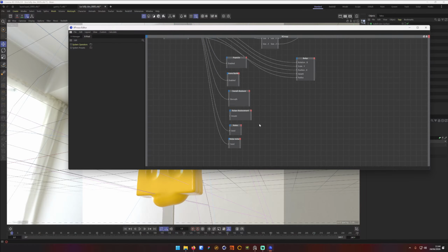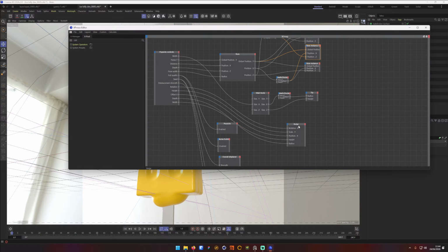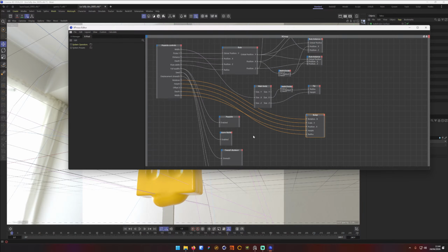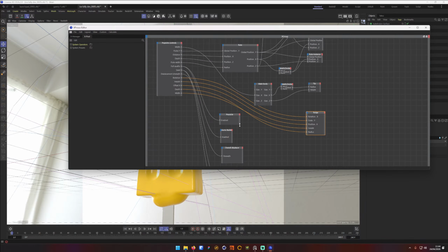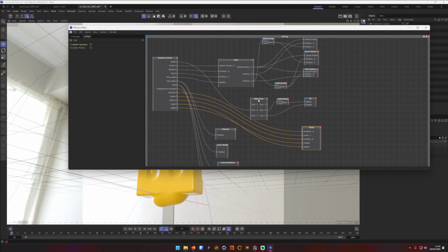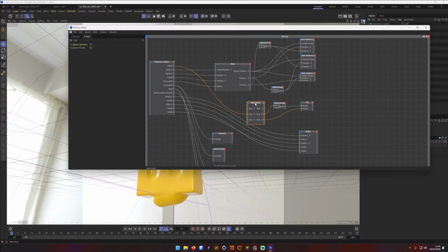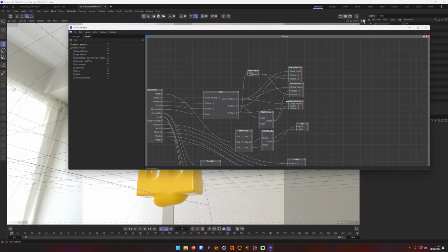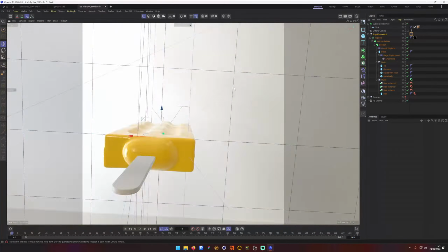So it's very scene nodey. If you've not done any node stuff before, this might look intimidating. It's really not. You expose the name of a control, pull in a property from an object, and then attach things together. You've got things like normalizations, but let's double click this. Node Editor, where is it? Oh, I'm so out of practice. There you go. Math, divide. So we've got these little operations we put in between. Xpresso is pretty easy, and you can build little rigs like this very quickly.